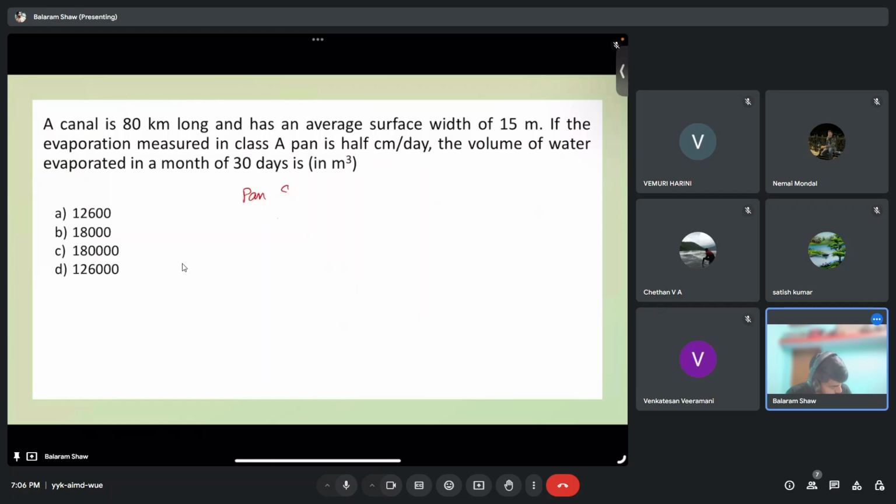So total volume of evaporation will be this depth of evaporation, that is 0.032 meter, into the water surface area. What is the area? Area is 100 hectares. 100 hectares as in 10 to the 4 meter square, right? So 1 hectare we know it is 10 to the 4 meter square. Just multiply this into 10 power 6. So it's coming as 32,000 meter cube per day, as in for that day. So the correct answer will be B. I hope you guys are getting the same, right?